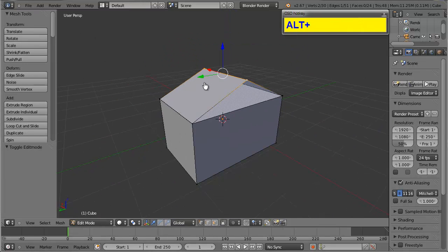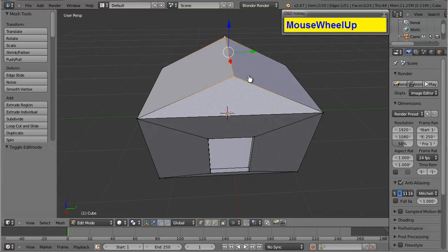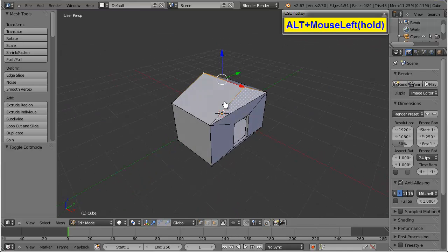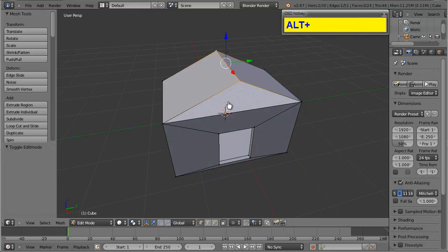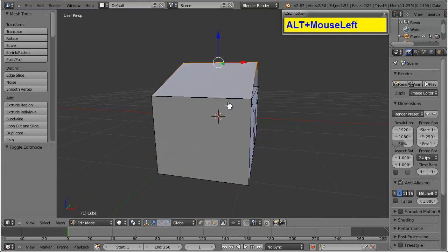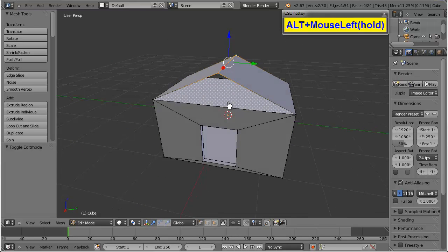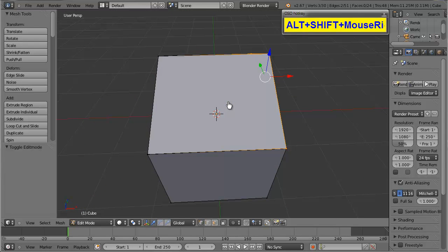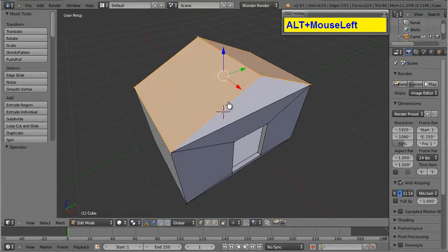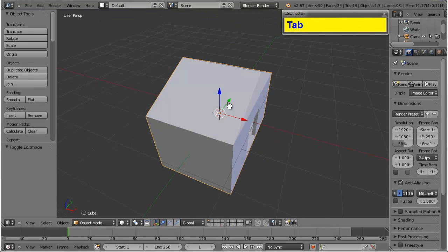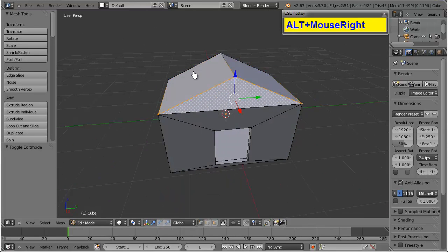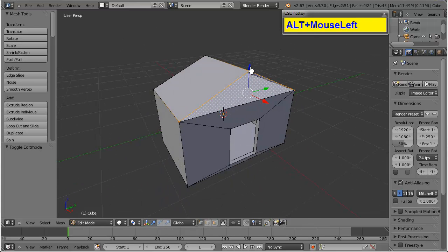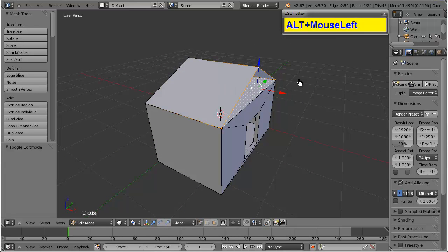Now, pardon me. Because roofs don't actually sit on here like this, they hang off the side some, I'm going to select all these vertices. Wait, actually before I do that, I need to do one more thing. I need to fill these in. To select all the vertices like that on that one side, I'm holding Alt while I right click.